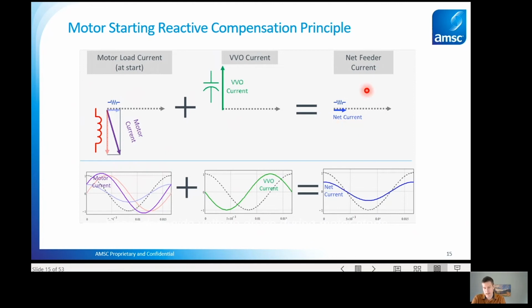And then we do have a little bit of leftover real power. That leftover real power is generally not a problem at all because it's the 600% inrush that we're fixing, and for the rated real power current that's remaining, the utility system and the whole industrial plant is designed to supply that steady state real power without creating significant voltage drops. So basically, when we fully cancel the reactive power, we end up fully solving this problem.